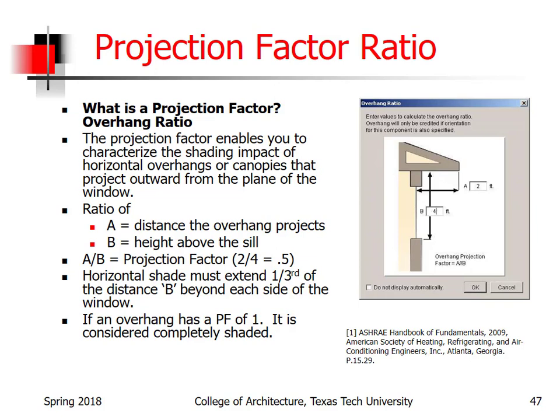And if you want a full glass window, then what you have to do is calculate the savings that you get from having that window, using it as daylight or whatever. But if you don't show them that you can keep the same level of energy usage as you would have with just 25% window, then you can't increase the amount of window in the building. So that's something to really think about, because a lot of us, when we get into designing, all of a sudden we want all this glass and stuff like that.